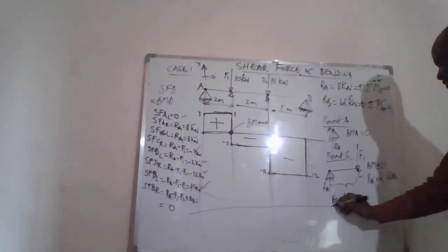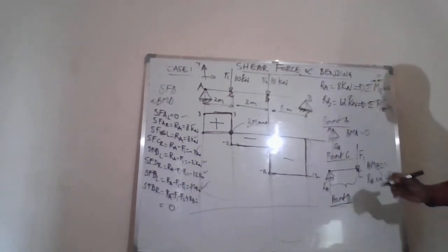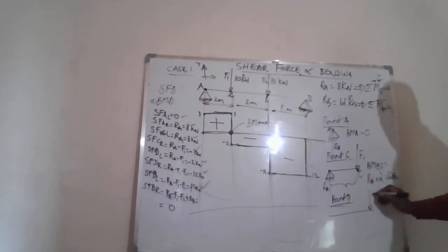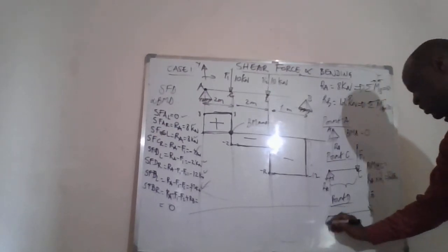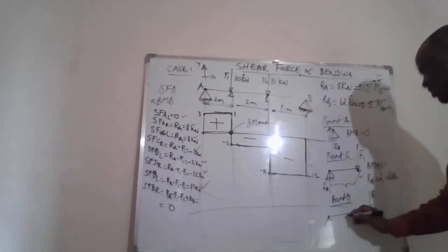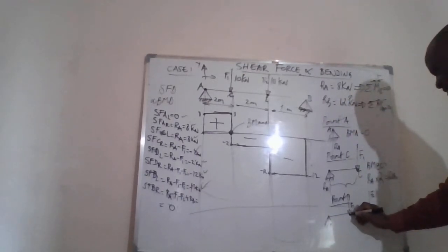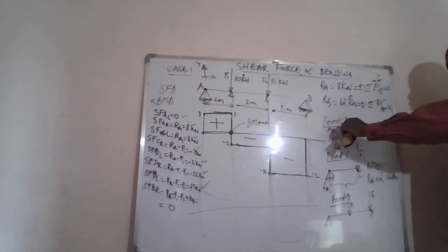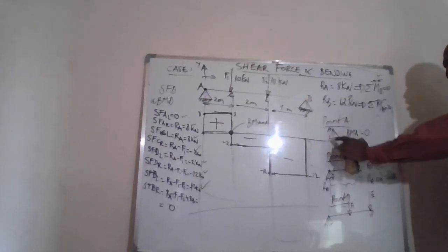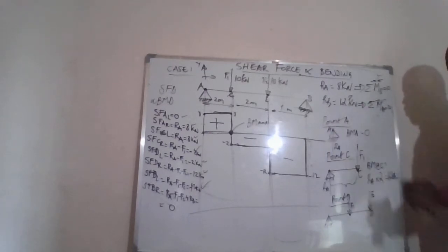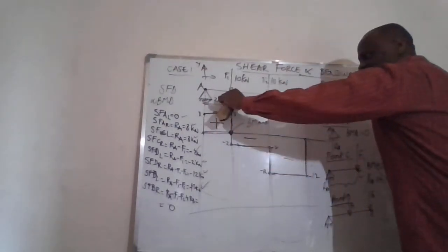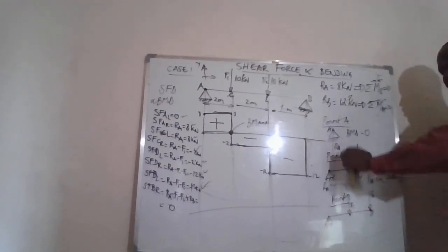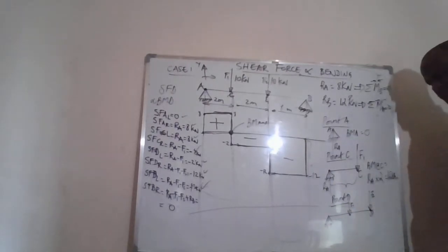Now, if we move to D, point D, we can see the free body diagram. If we are at point D, we'll have something like this. At D, we have F2. We still have at the left the reaction. We still have F1 at C, and our new pivot is D. The first pivot was A, and we only have one force on A, which is the reaction, and the moment was 0. We move to the next pivot, which is C, and at the pivot C, it's only RA that creates a moment because F1 is on the pivot.